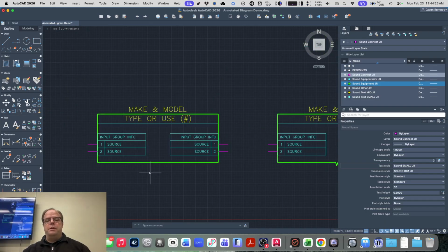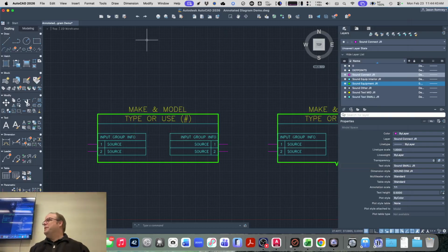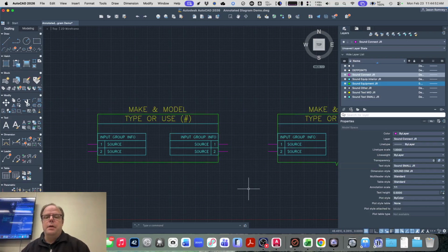Now those lines will always be thicker, which is good. And you can notice in my example, if you now look carefully, you can tell that those lines are just a little bit thicker than the other ones. And I think that makes it look a lot nicer. But it also fixes my overlapping line problem, because sometimes you need those overlapping lines. I don't want to get rid of them because I need those snap points. So there you go. And then you can turn off the display line weights later.